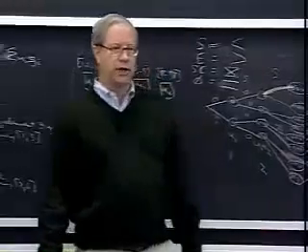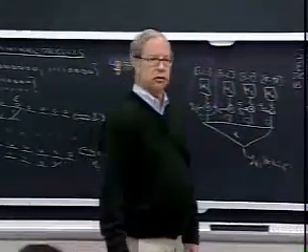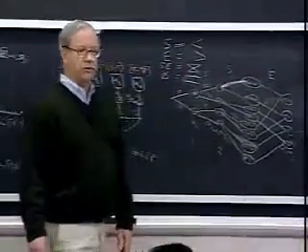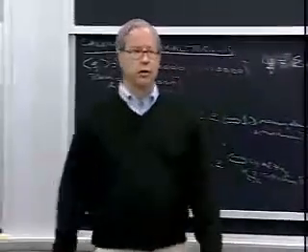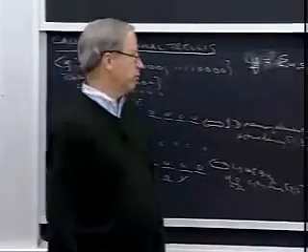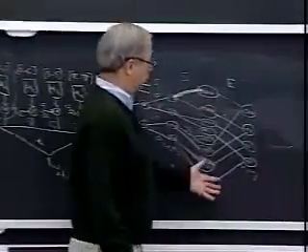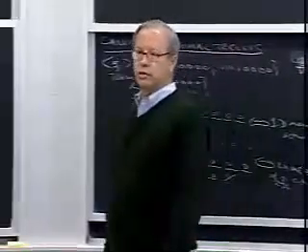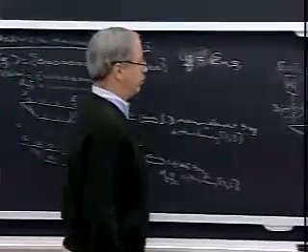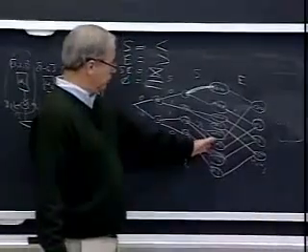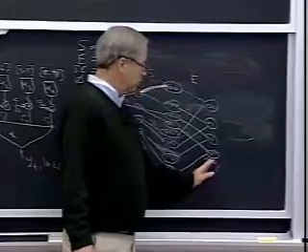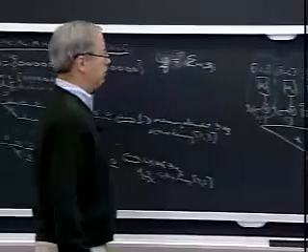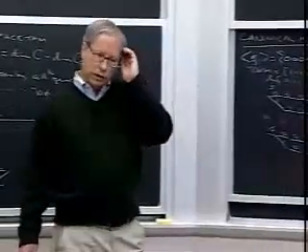But actually, when you're asking what's going on in the Viterbi algorithm, what does the Viterbi algorithm have to do? At a minimum, it has to do one thing for each branch. It has to perform a metric extension, a metric addition computation, at least once for each branch. So the Viterbi algorithm complexity is better estimated by the size of the branch space than the size of the state space. To progress at this point, a Viterbi algorithm has to do at least 8 things. To progress again, it has to do at least 8 things. All right? So it's more relevant from the point of view of complexity.